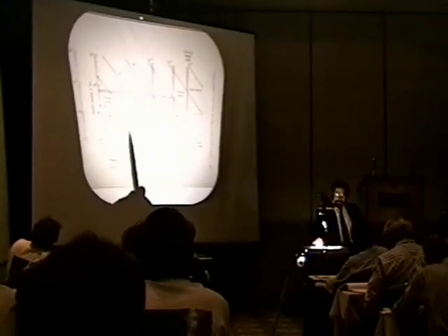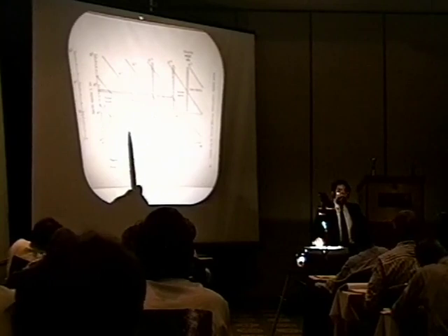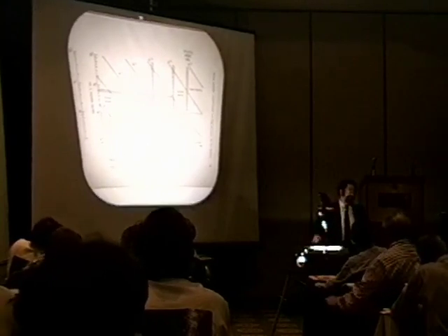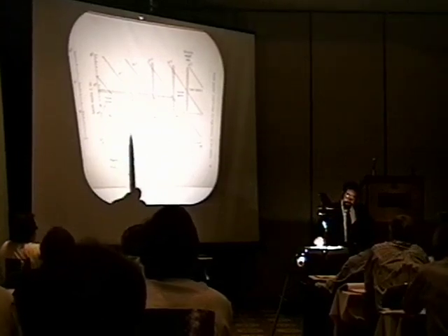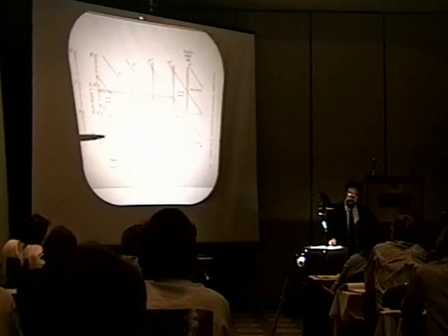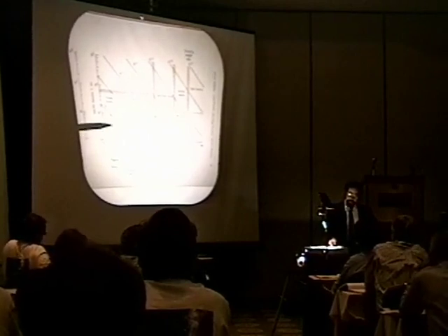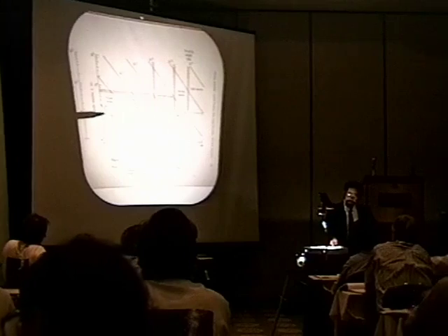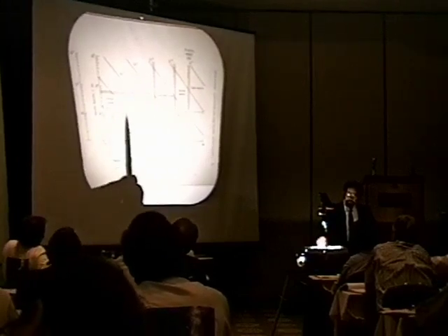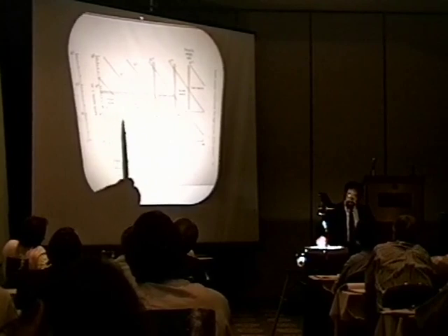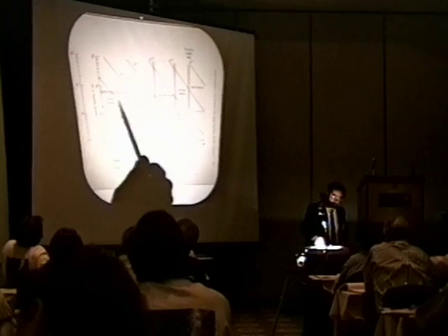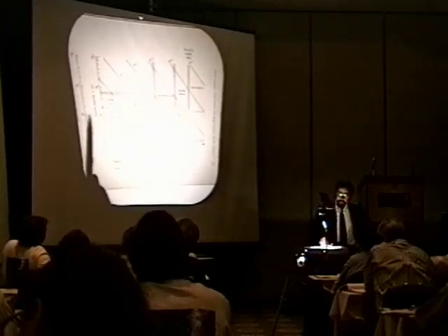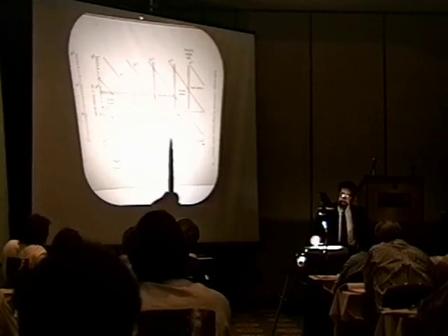Chemical rockets are here, very high thrust-to-weight, the thrust is 30 to 60 times the weight of the engine, or the mass of the engine. Chemical rockets are down here, but they're limited in specific impulse. Solid core rockets, fission rockets, go higher specific impulse, and still pretty hefty thrust-to-mass ratios. That's type 1 propulsion, okay? High thrust-to-weight generally, and limited by specific impulse.